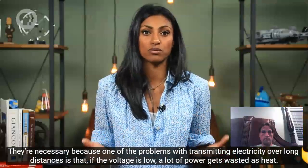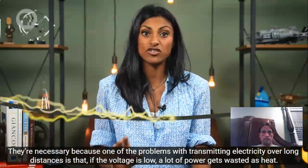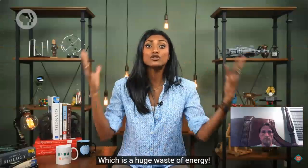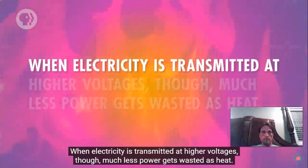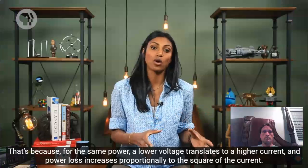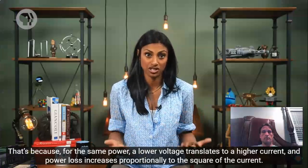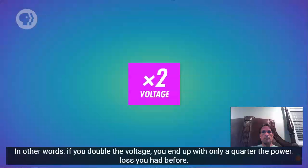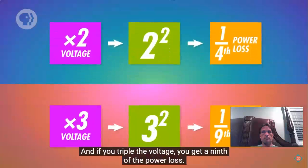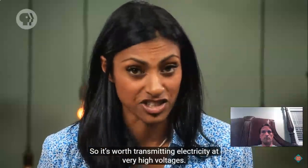They're necessary because one of the problems with transmitting electricity over long distances is that if the voltage is low, a lot of power gets wasted as heat. We're talking like 80% in some cases, which is a huge waste of energy. When electricity is transmitted at higher voltages though, much less power gets wasted as heat. That's because for the same power, a lower voltage translates to a higher current, and power loss increases proportionally to the square of the current. In other words, if you double the voltage, you end up with only a quarter of the power loss you had before, and if you triple the voltage, you get a ninth of the power loss. So it's worth transmitting electricity at very high voltages.